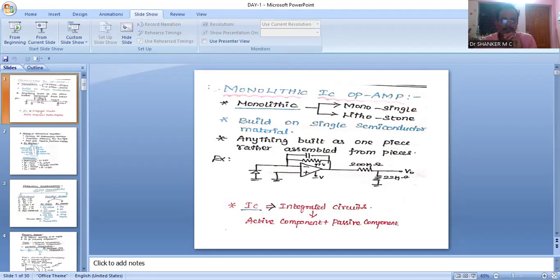The slew rate we can usually mention in terms of frequency and amplitude, that is 2 pi fm Vm. For example, if Vm is 4 volt and fm, the frequency, is 30 kilohertz, the slew rate will be around 0.1884 volt per microsecond.